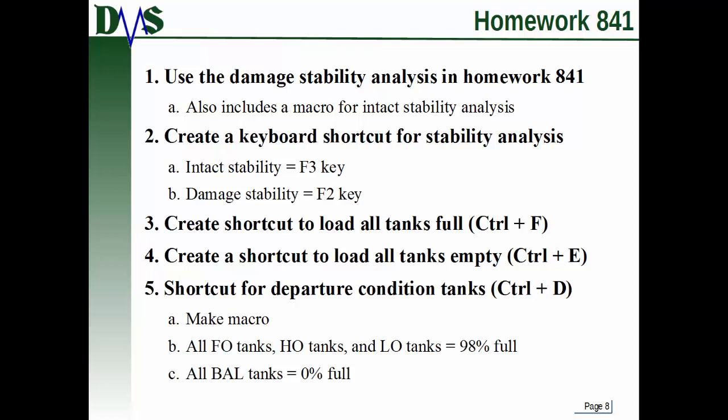And then once you've done that, I've got a few more keys that I want you to create. First, I'd like you to create a shortcut key to load all of the tanks completely full. So that'll be Control F. You'll have to create a macro yourself, or your own keyboard command, and then assign it to the Control F key. Same thing to load all the tanks completely empty. So again, you'll have to do a Control key there and assign it to that Control E key.